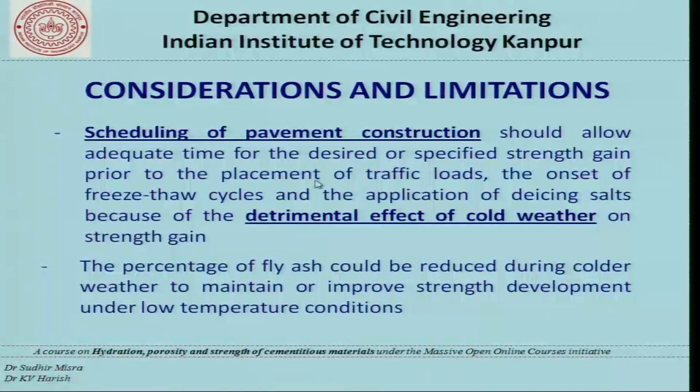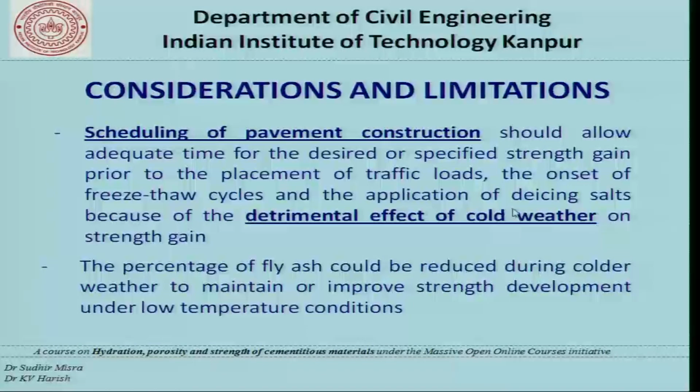One is that we want the pavement to gain strength as early as possible so that it can be exposed to traffic loads. Remember that if we want to expose to traffic loads, then the pavement should have gained substantial strength. Because we are using fly ash, and that too we are thinking of using in cold weather, the strengths will be lower, and hence it becomes a disadvantage to use fly ash for such application. Likewise, when we are talking about freeze thaw cycle, we need a quick strength at early stages, and this also causes problems.